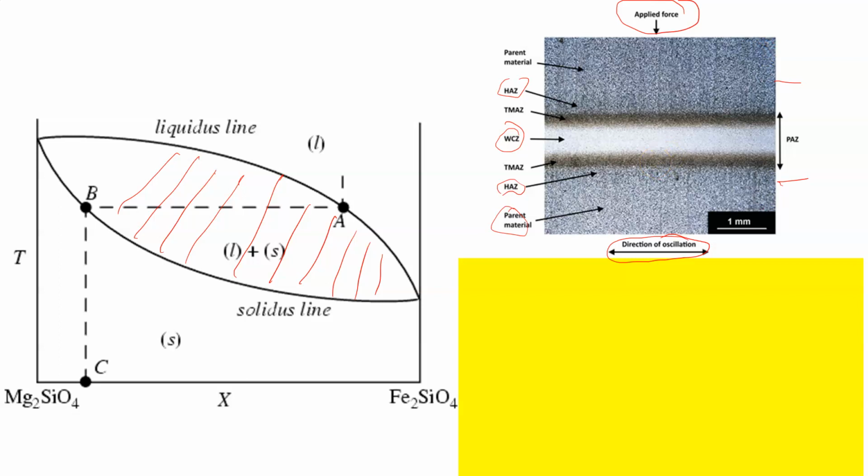So the metal will actually be brought up, and with that relative movement, you have some recrystallization. Now, another thing about this movement, you end up with a phenomenon known as dynamic recrystallization. What happens there is that you're actually crystallizing because of that motion. This is where you see certain processes known as friction welding, where you're actually moving the two parts around each other, and that's what causes the bond to take place.